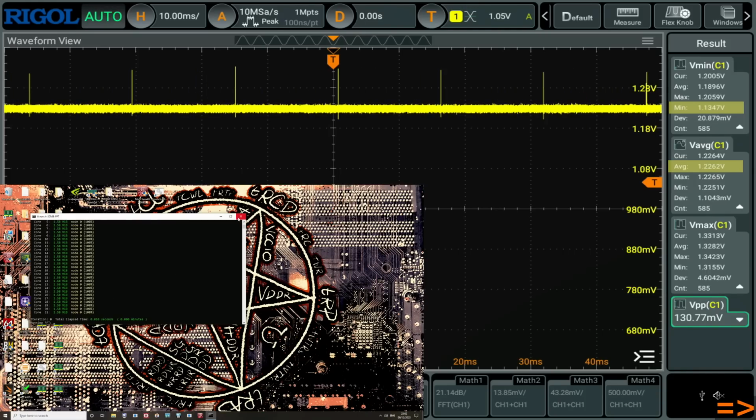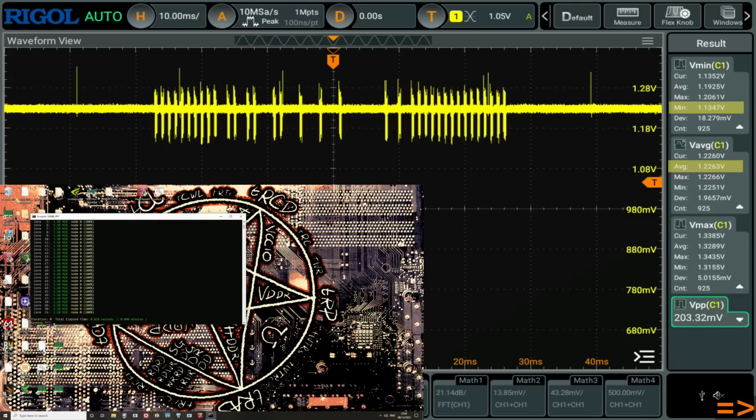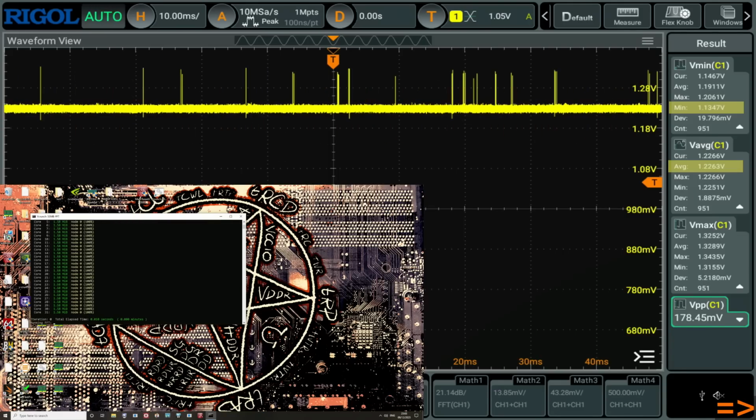And the funny thing is, you might be wondering, wait, why would a 40 millivolt increase in V-droop lead to a roughly 40 millivolt decrease in undershoot? And that's just sort of a thing that I've noticed with some motherboards. It's not universally true, and generally as your load line calibration gets more and more aggressive, the undershoot gets disproportionately worse. But yeah, so this is still unusable.